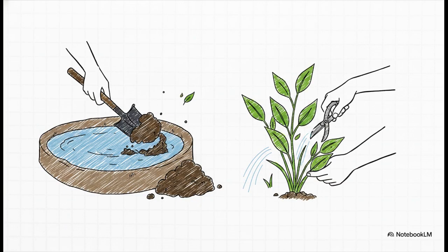Now, the absolutely crucial takeaway here is that these stormwater systems aren't magic, and they certainly aren't set and forget. I mean, you wouldn't build a massive highway and then just never pave it again, right? You have to treat these vegetative controls and traps like vital living infrastructure. That means rigorous ongoing maintenance. You have to physically remove accumulated sediment from the traps, actively repair erosion in the outlets, and meticulously maintain the health of the plants. That is the only way to ensure they actually remain effective year after year.